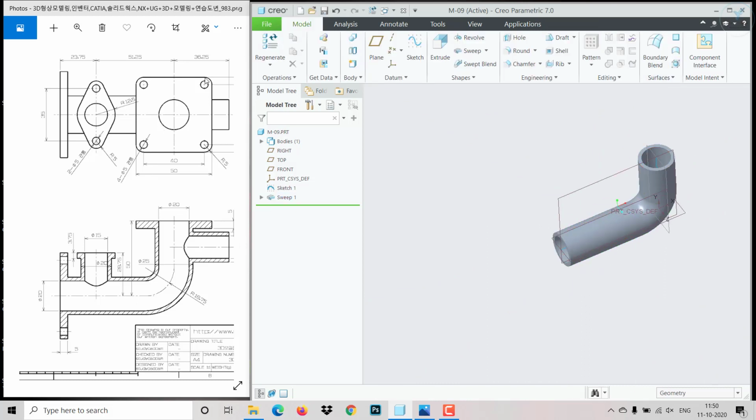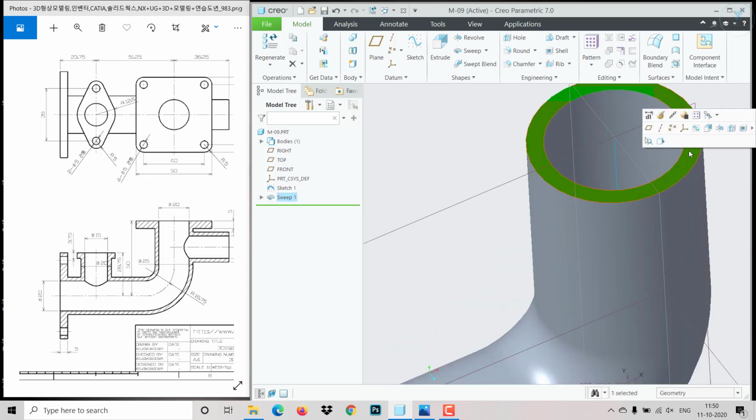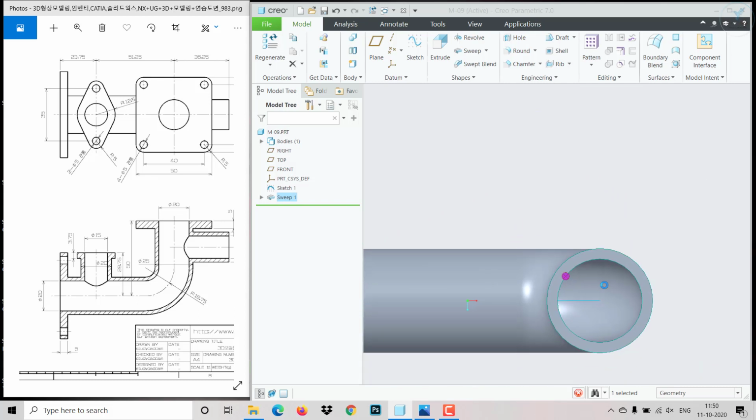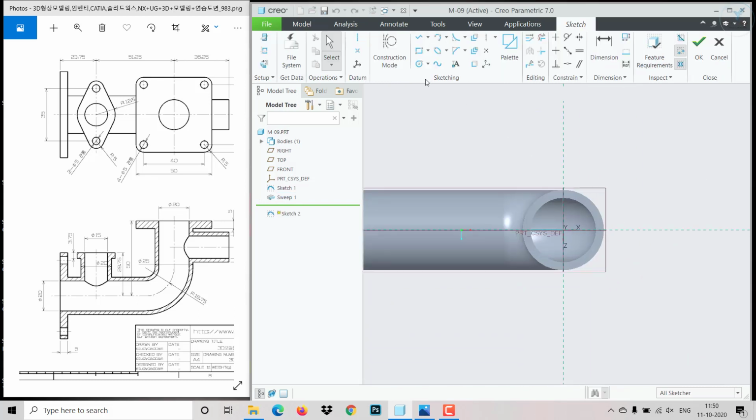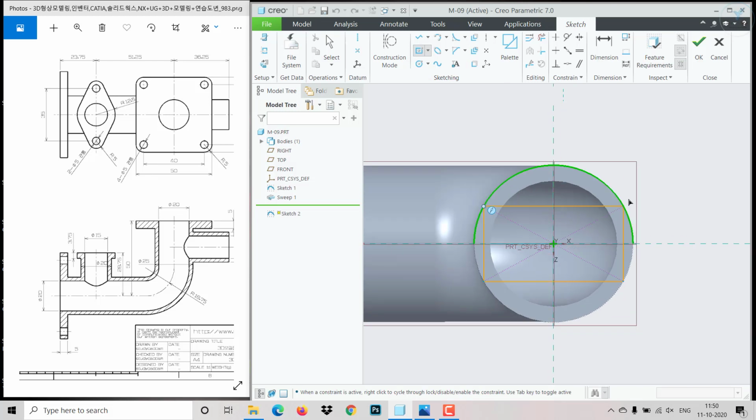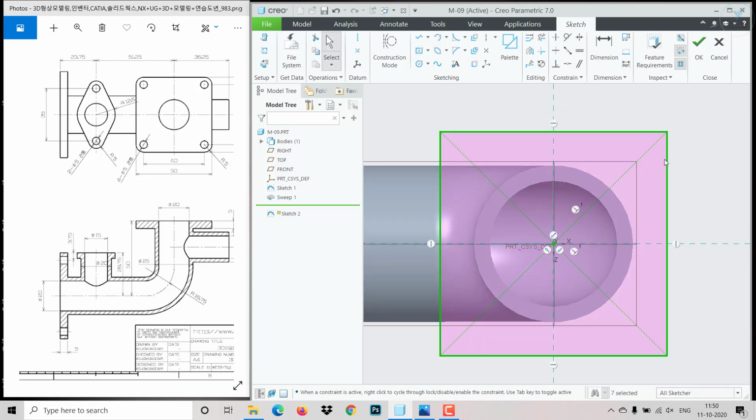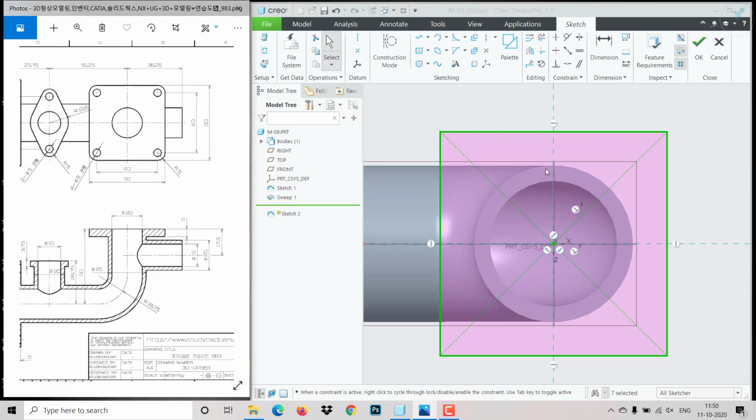So now on top we need to create this rectangle square shape over there. So click on this face and then click on sketch. Now we need to go for center rectangle. Specify the center point, position it. It has 50 cross 50. So go for dimension, or before that specify fillet on all the edges.